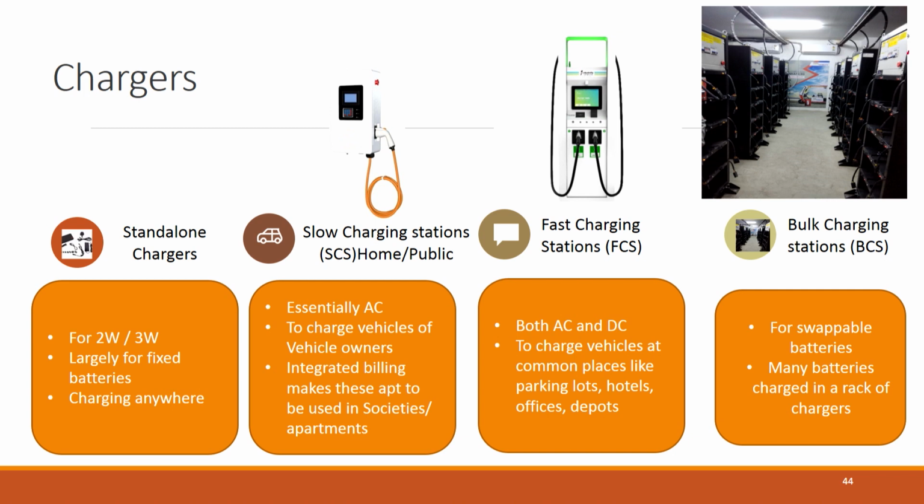Now, one important part is that whenever we hear about slow charging or fast charging, it is very relative. It has nothing to do with the C rate of the charger alone. It depends on both the charger and the battery. If the battery supports charging at more than, let's say, 1 C rate, we say we are able to charge the battery at a fast rate.